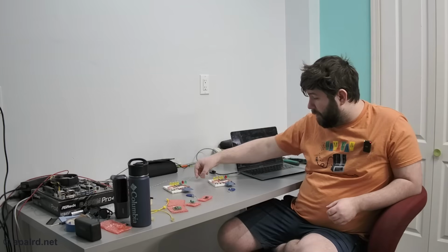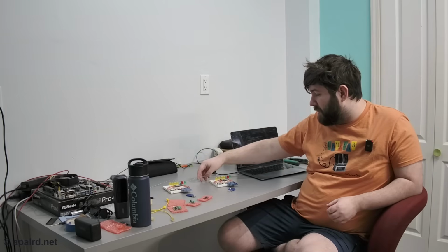So back in the days of a CAN bus, essentially all of our transmissions were broadcast. We had IDs, they were either 11-bit or 29-bit, which is kind of a weird number, but whatever. And we would just know that each ID means certain bits of data. We couldn't format the data with something nice like JSON or XML. God, XML wastes so much data. With only 64 bits per message, we had to bit pack everything we needed. And then on the bus, we would say, like, I want message number 72, etc. And we didn't have essentially more meaning to that.